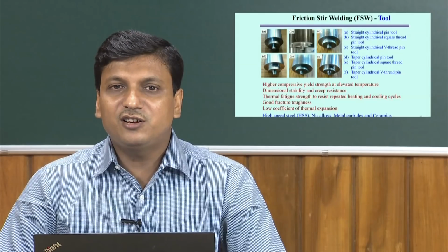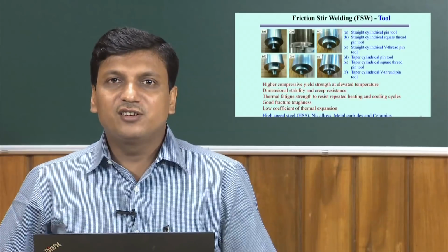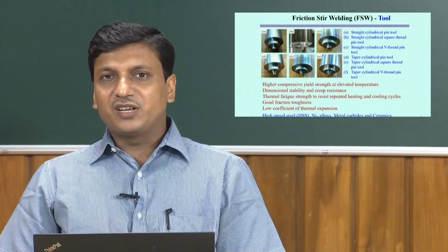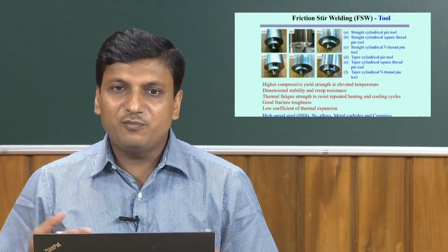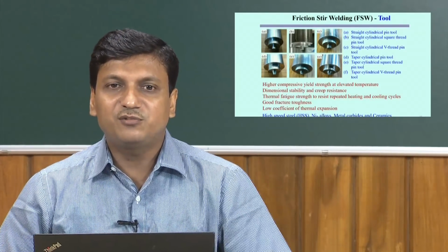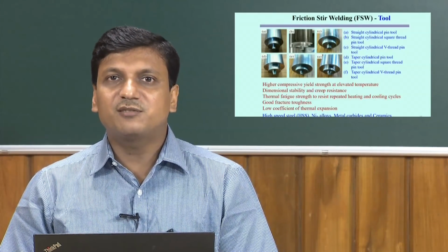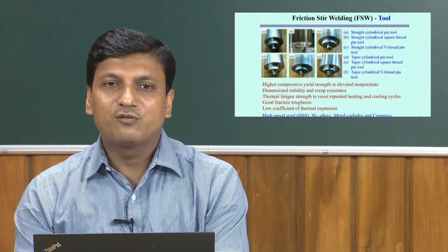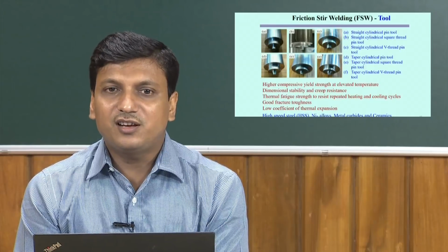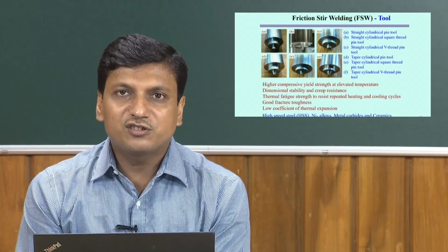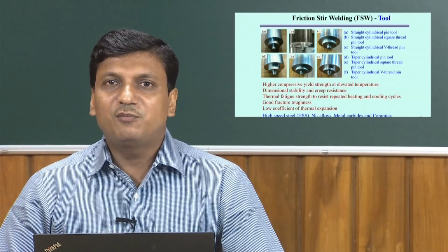That is another desirable property of the tool material. Thermal fatigue strength should be very high, because this tool material is always in repeated heating and cooling cycles. That repeated heating and cooling can create some kind of thermal fatigue. So good thermal fatigue resistance, good fracture resistance, and of course low coefficient of thermal expansion, all of these are desirable properties of a tool material.